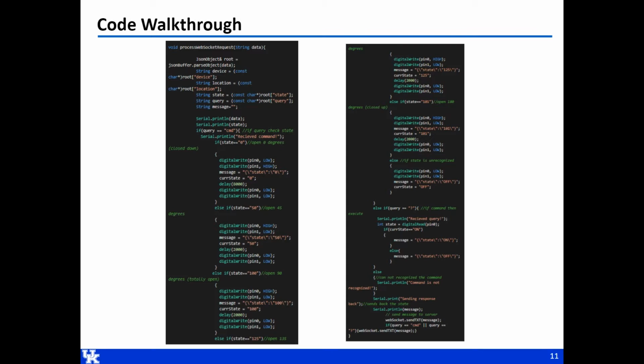And after the delay, the pins are then back to low. So what this will do is this digital write, low and high, will turn on the H bridge. Then it'll delay. Of course, we'll go down to one that will actually run. It'll delay 2 seconds. So that way the motor will be on for 2 seconds. And after that delay, it will write low to both pins, which will then turn the H bridge off and will, of course, turn the DC motor off.